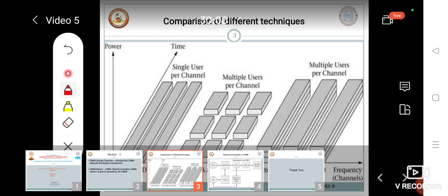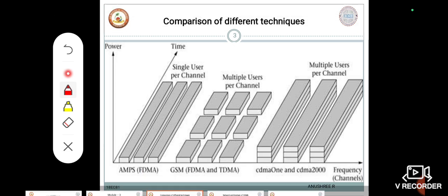Now coming to the CDMA frequency bands. Let us study how the frequency bands are going to be selected for CDMA. For 2G CDMA systems, one might be inclined to state that the frequency separation between the adjacent carriers or channels is 1.25 MHz. In CDMA standards, the terms carrier and channel are carefully distinguished from one another.